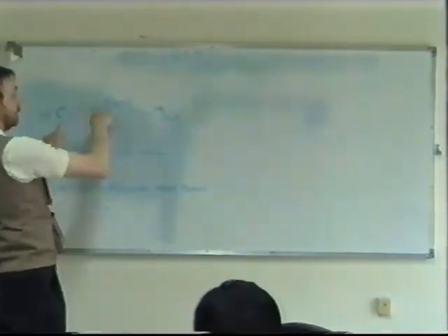This is meant to be a dead straight line, of course, between the two. Square root of TX height and RX height, yes, that's exactly it. Beyond the distance between the two, you lose your signal because of the horizon. So it's the maximum theoretical range, and of course if there's anything situated between the two, you're going to perhaps lose your signal depending on what's there.